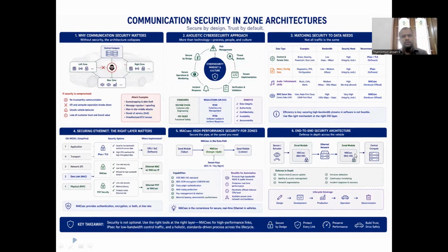Then there is unauthorized ECU access. They can influence the ECU memory without any security access. By default, in every automotive ECU, they implement something called security. When you want to do some manipulation in the ECU memory, first you have to move to a certain DIAG session, probably extended or programming. After that, you have to gain something called security access.